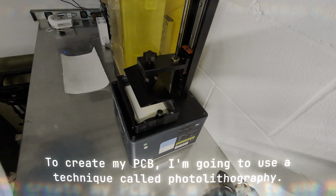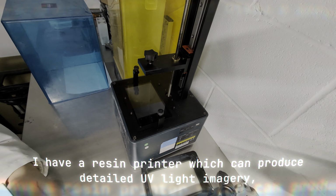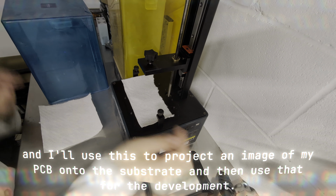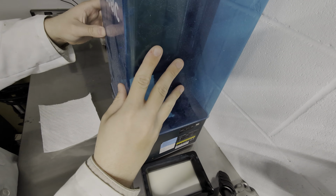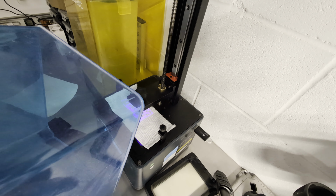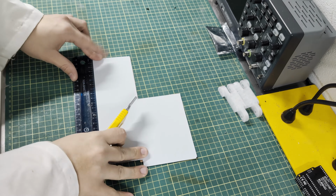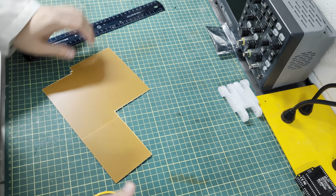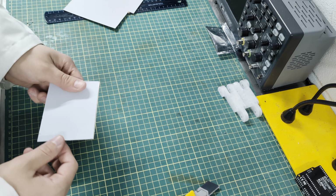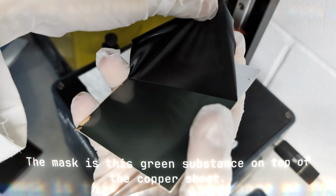To create my PCB, I'm going to use a technique called photolithography. I have a resin printer which can produce detailed UV light imagery, and I'll use this to project an image of my PCB onto the substrate and then use that for the development. This mask is this green substance on top of the copper sheet.